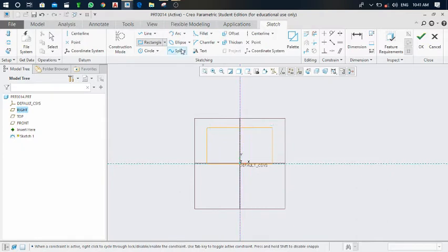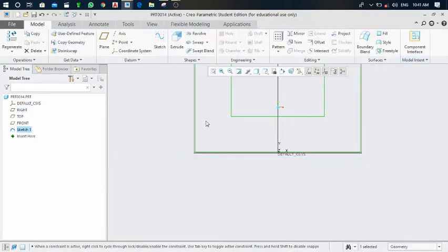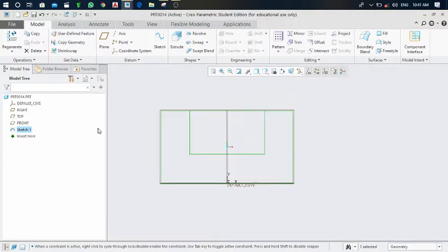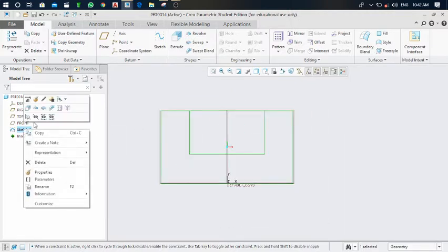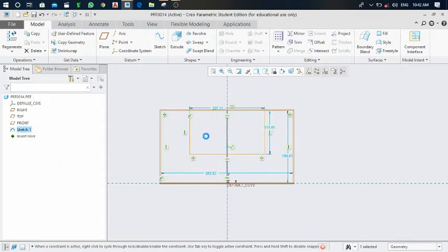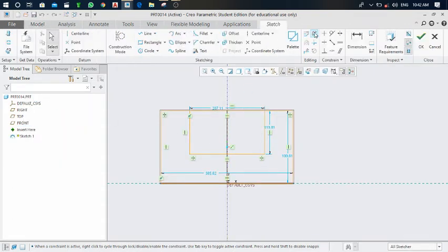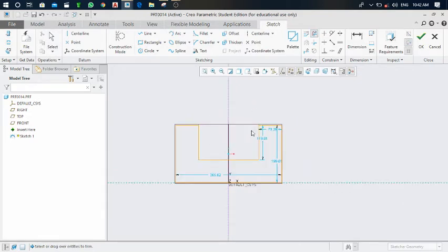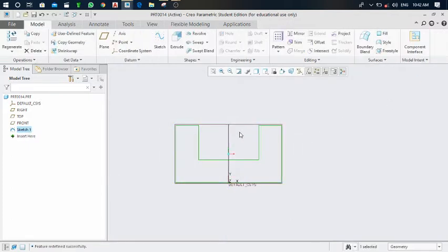Here you can see, take again rectangle and draw it from here to here. Okay, click on this OK. But this we have to again go to this sketch and click this edit definition, and here is one option, delete segment. So click on this and trim distance position and distance position. Okay, and click on OK.